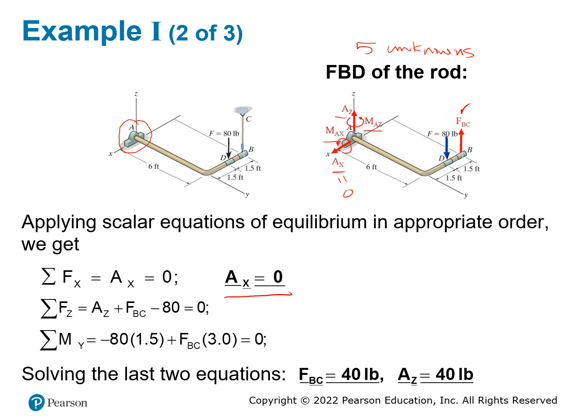And then you can sum the forces in y, which is the force of AD and BC and AZ. You sum them together and it is going to be equal to 0. So that's the second equation that you can come up with. The third equation, you cannot use the sum of forces in y because there's no y component force here. So you have to use one of the moment equations to do that.